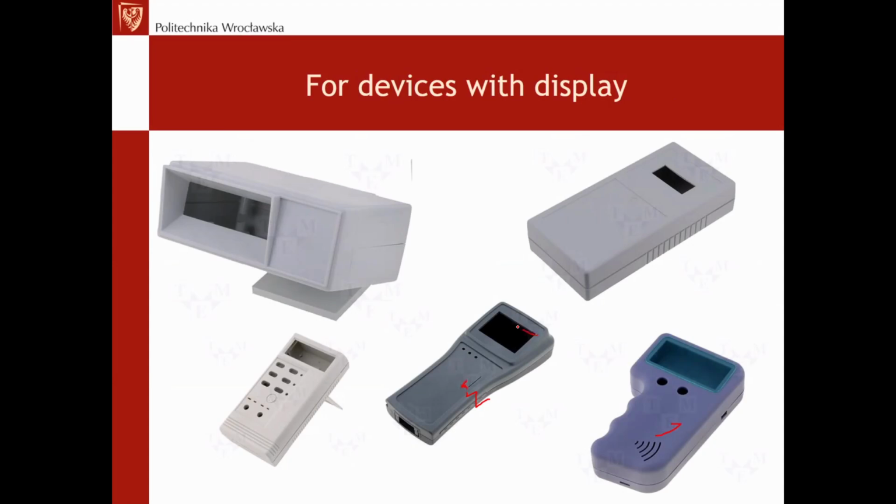Which does mean that if you want to use such a case, if you are not afraid of this case disappearing from the market, then you have to take the case before or at the very early stage of your design process, and you have to adapt your PCB design and electric design sometimes to the case itself.